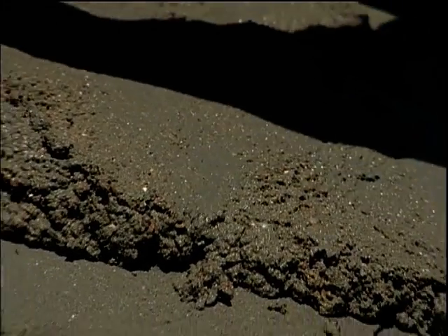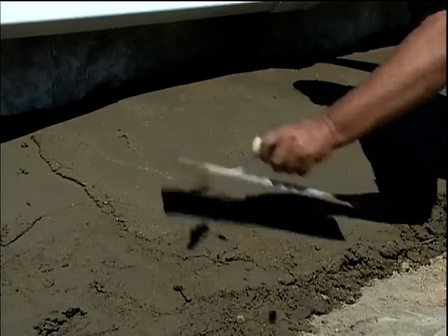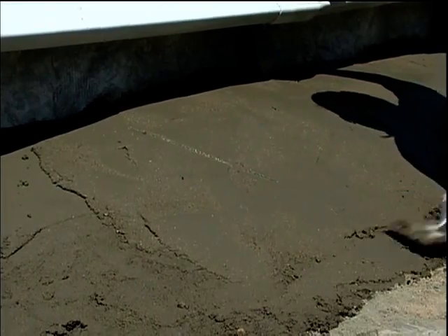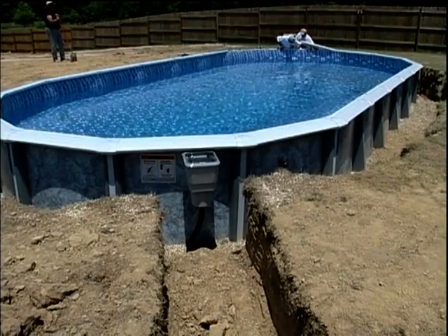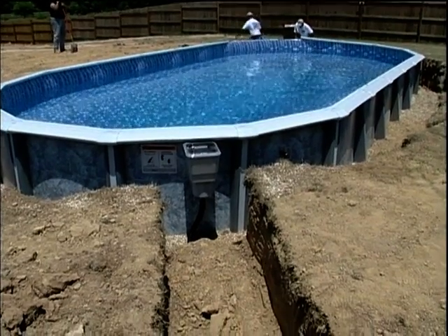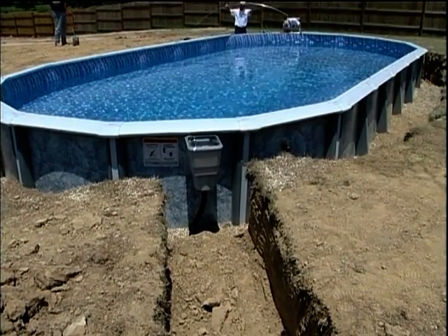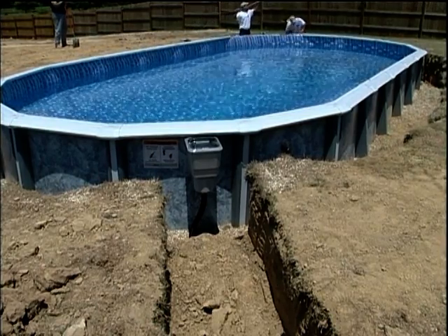Once the slurry is compressed and filled to the proper level, smooth out the slurry mix, sloping away from the pool. When backfilling around the skimmer, if you are hard plumbed into the skimmer, you may choose to backfill completely around this area. Another option is to form the backfill around the skimmer to allow access to the piping.